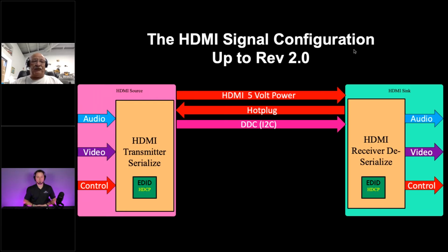A lot of people don't think about it. We see so many products come in where, especially in wires and cables, they take those DDC lines and they make them into crap because it's a low end. It's only 100 kilohertz. Now 100 kilohertz is high. It's a lot higher than audio, right? But we're dealing in the gig range on HDMI, so 100 kilohertz is nothing. But there are some rules under I squared C that many people don't follow.